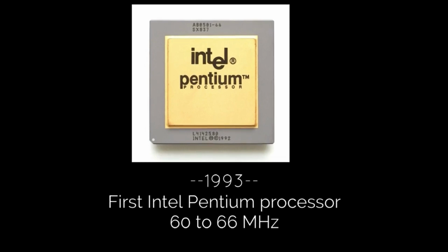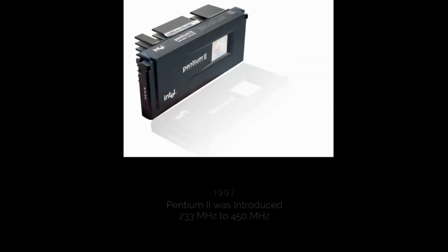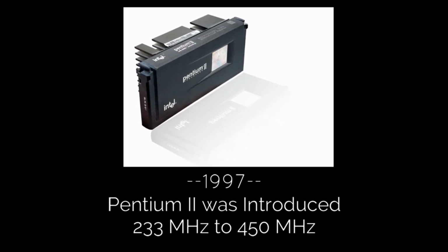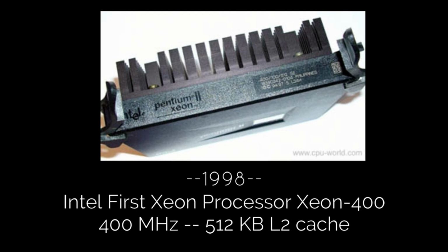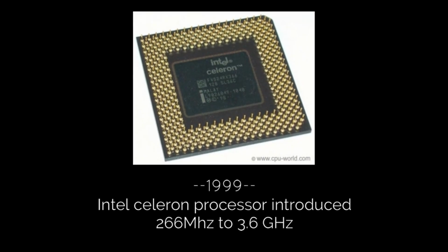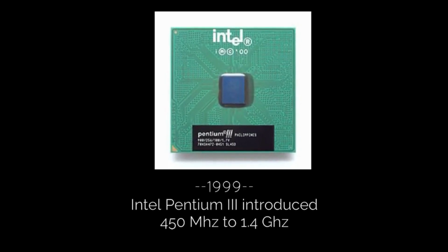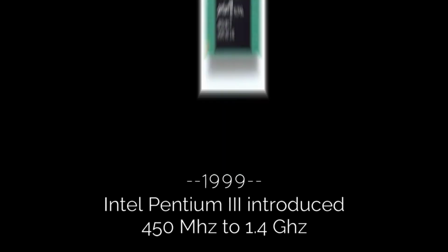Now, let's look at the difference between CISC and reduced instruction set computer, or RISC, architectures, emphasizing the advantage of CISC in supporting a robust instruction set. The Intel 8086's performance was enhanced through techniques like prefetching and the introduction of the 8087 floating point coprocessor for efficient floating point math operations.